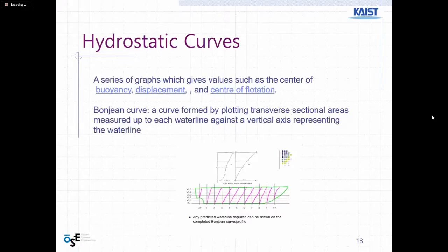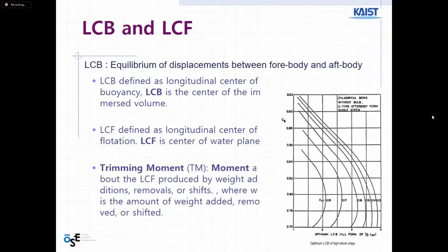I wanted to put simply what hydrostatic curves are, and what sort of information you can extract from them. Hydrostatic curves give you information about the buoyancy, about displacement, and center of flotation. And one of those hydrostatic curves is the Bonjean curves, as you can see down here.